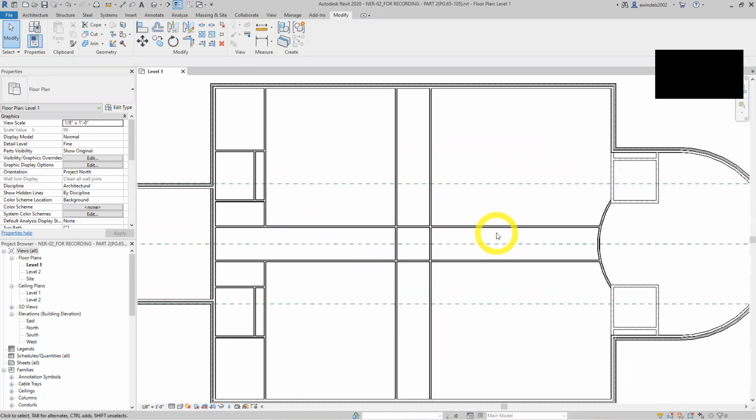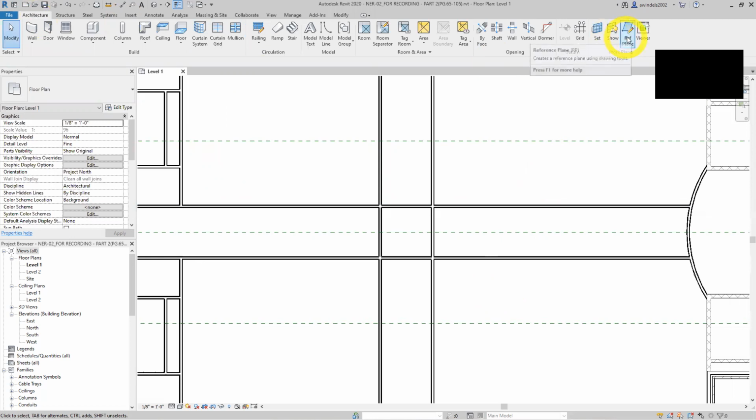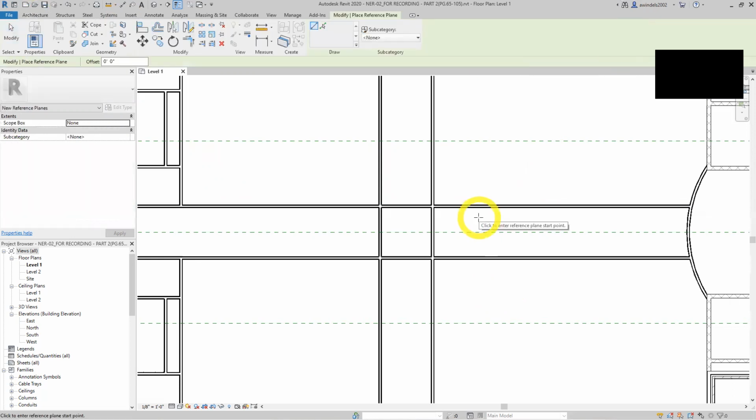We're getting there. We're on page 75, and we're going to look at the intersection of this corridor. We're going to draw another work plane panel to draft about, and you'll see the power of why I do that in a minute. We're going to create some 45-degree walls to open up the corridor in this area. We're going to draw another reference plane. So we're going to go to the architecture tab, reference plane. And we're going to do the pick lines button and 4-foot offset. You can do positive or negative on these to go left or right initially.